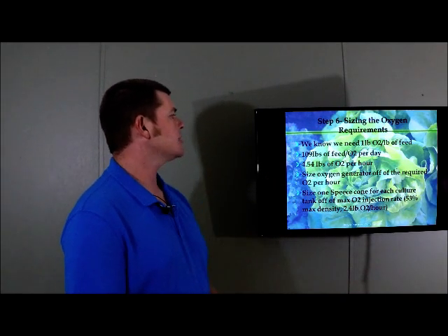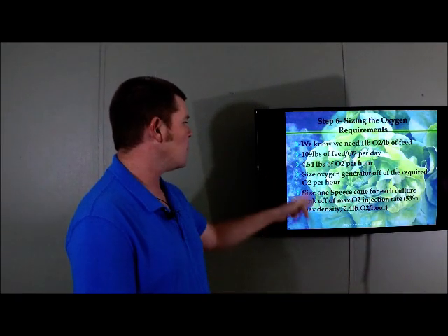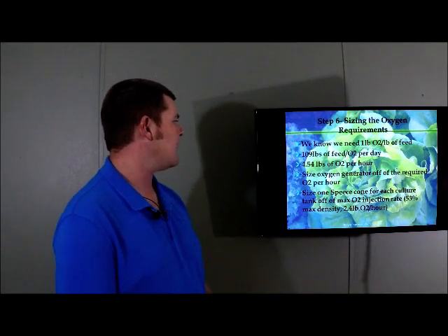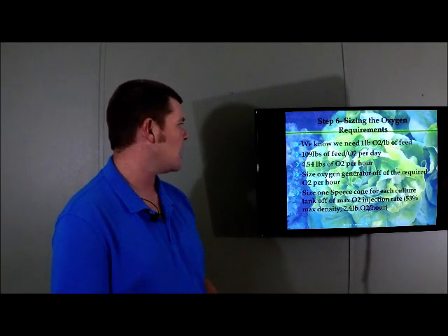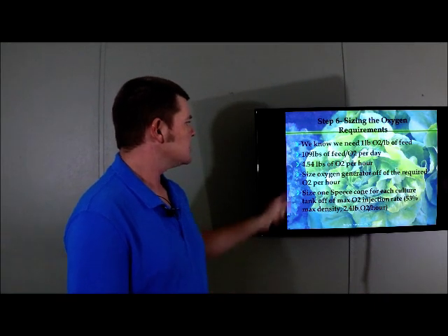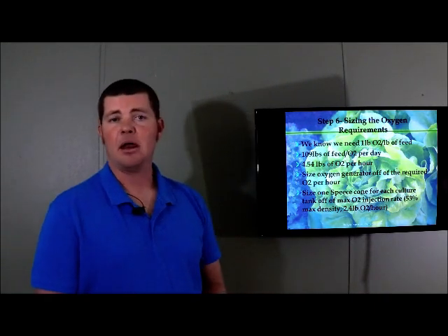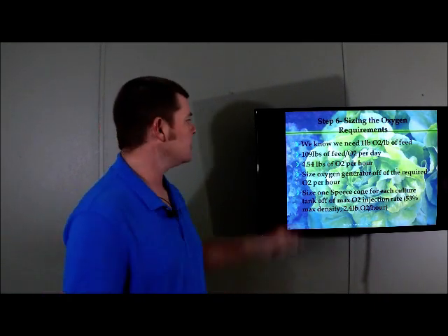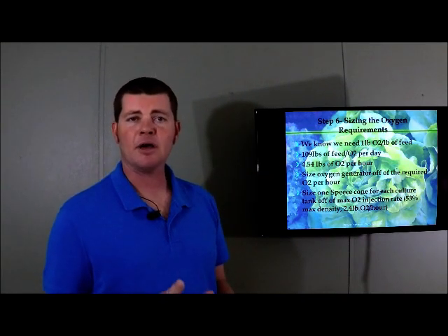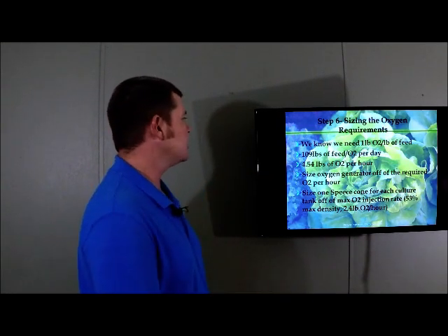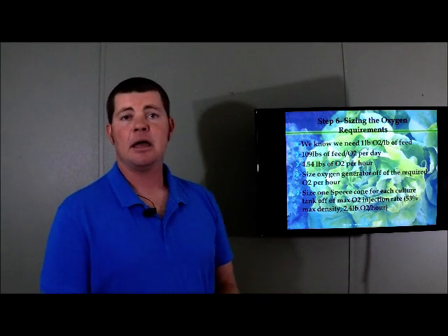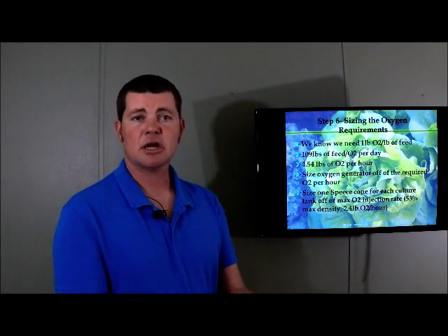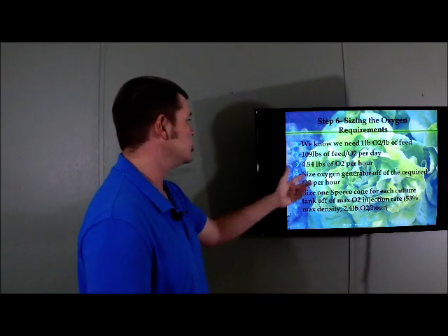Now we can size our oxygen generator off of this requirement. We know we need 4.54 pounds of oxygen per hour. So size the oxygen generator off of that. When you go to buy an oxygen generator, they'll sell them in pounds per hour of oxygen. Very easy. And you can buy either a positive suction or a vacuum type oxygen generator.